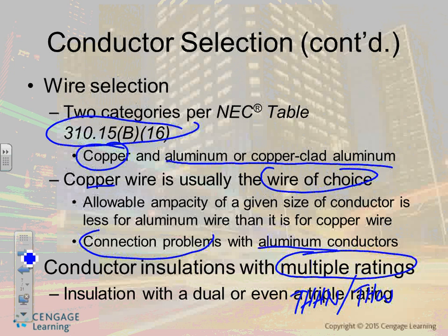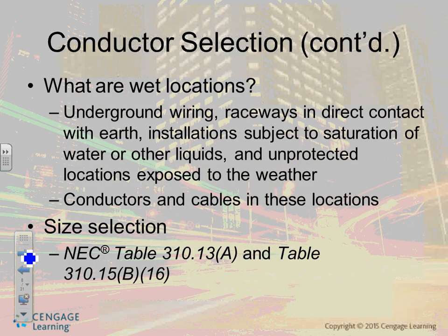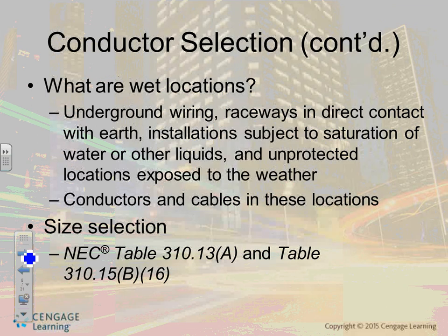Remember, there are other things other than water that can affect the insulation. Chemicals. If you put it in a chemical plant, some insulation, guys, you have to have a cable rated for chemical plants. You know, that's a whole specialty, basically. Okay, we talked about wet location. I always say I like the word that they use for wet location, saturation with water.